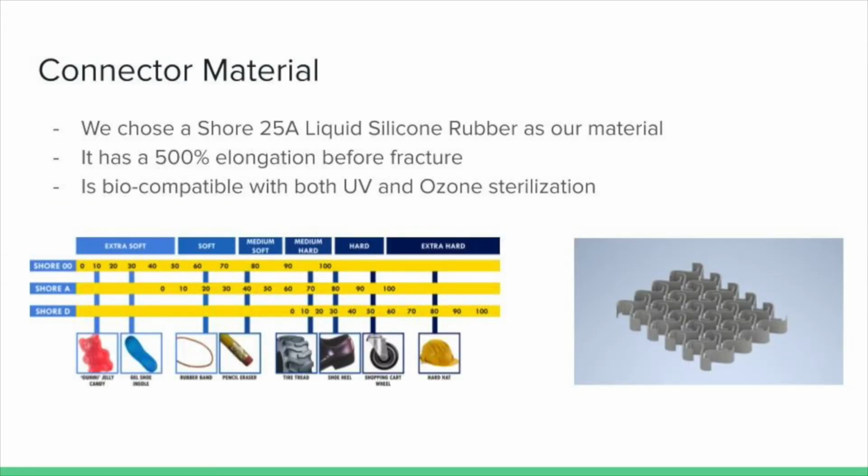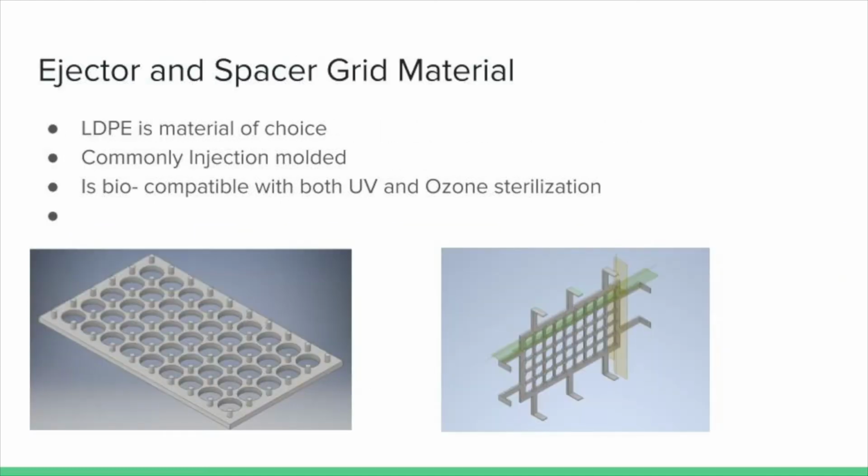For our connector material, we chose a Shore 25A liquid silicone rubber. It has a 500% elongation before fracture and is biocompatible with both UV and ozone sterilization techniques. For the ejector and spacer grid material, we chose LDPE. It is a commonly injection molded plastic and is also biocompatible with UV and ozone sterilization techniques.